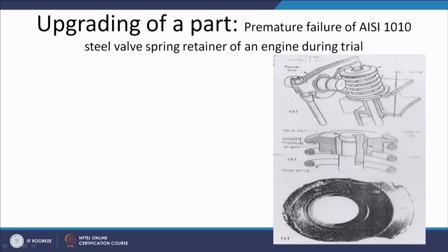And in this case we can see there are some junctions, the varying cross sections, and at the cross sections some fillets are there. So, these fillets will be used for having the gradual change in the loading and gradual change in the stress distribution.